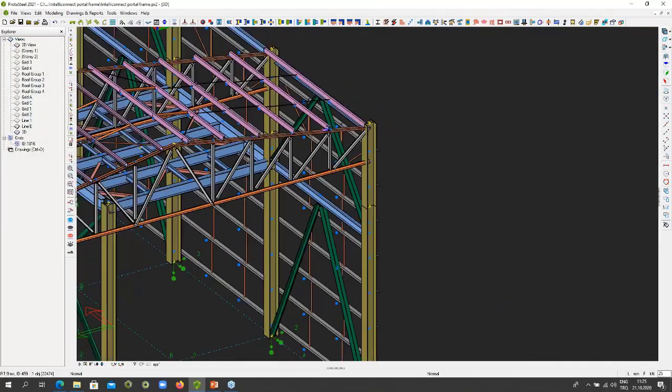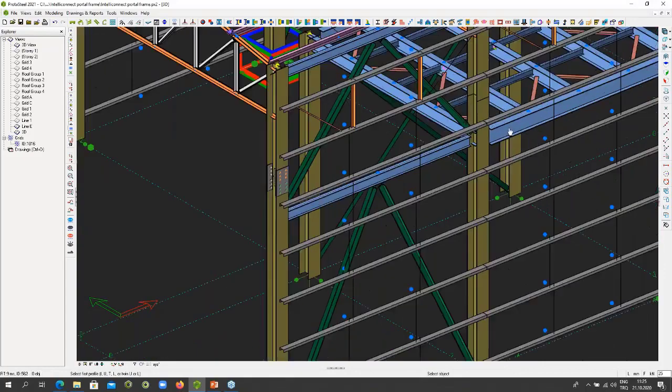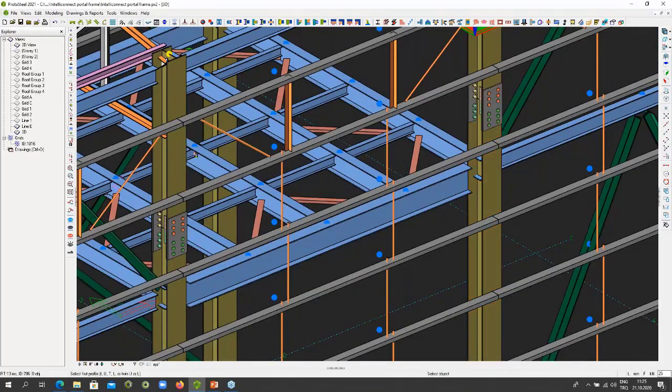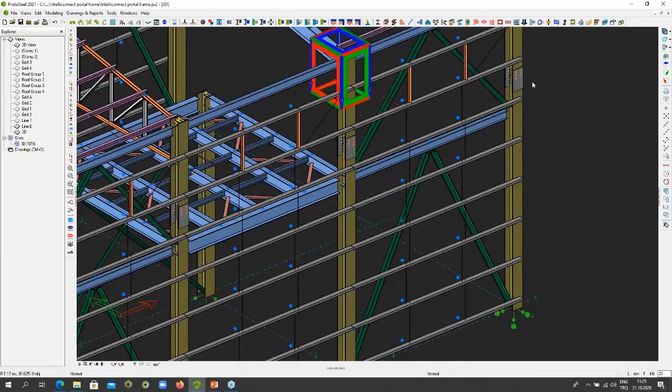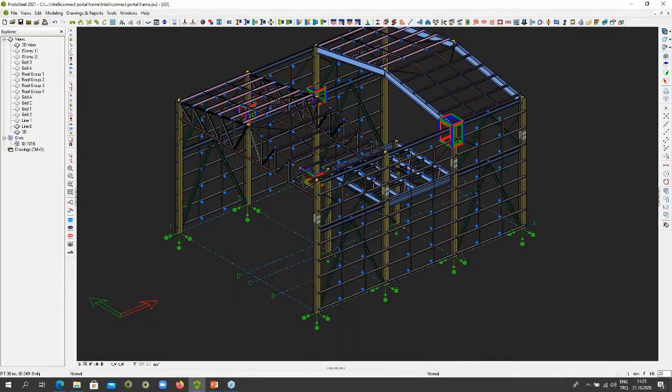Let me talk about splices, for example. So we've got several points in our model. So mind you, this model is now the final model. So the splices need to be in there. And just by clicking the 2 columns, we are able to create the splices on the go. Nothing is required. We're just pointing and clicking. I'm not entering the plate thicknesses. I'm not entering the number of bolts. Everything is being taken from my company standards, by some design algorithms, by the loads which I already have.